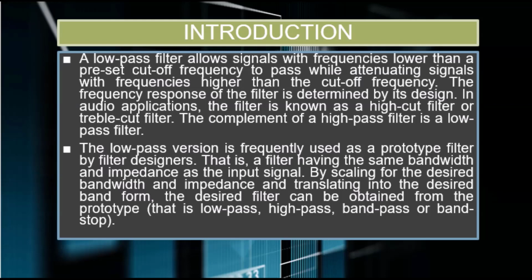The low-pass filter version is frequently used as a prototype filter in filter design. That is, a filter has some bandwidth and impedance, and the input signal is scaled for the desired bandwidth and impedance, then translated into the desired band.